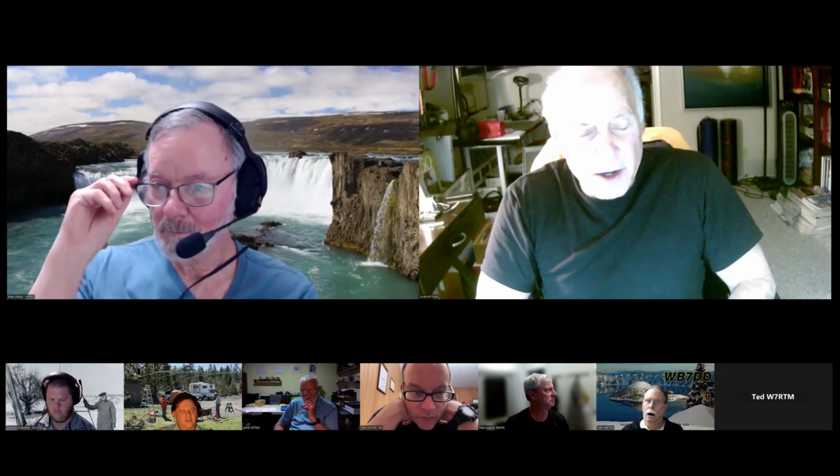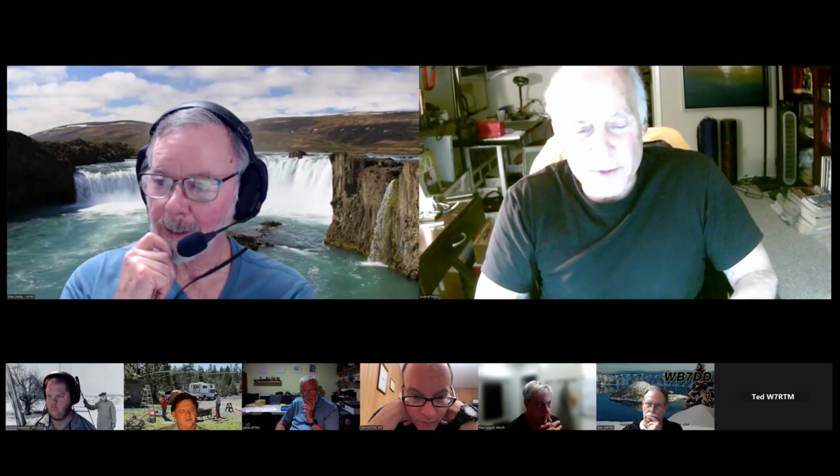He has several on one-to-one chokes for transmission lines and other types of baluns and ununs like 4-to-1, 9-to-1, etc. On the one-to-one common mode choke, he doesn't use a NanoVNA but a benchtop VNA. I've just taken my NanoVNA and basically copied what he did.